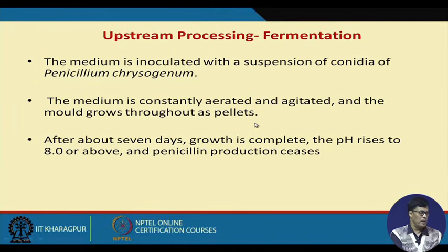Now, here again let me point out that in the case of fungal fermentation processes, we use the stirred tank reactor. In the stirred tank reactor, we use a mechanical agitator, and it has been observed that if we put the agitator on from hour 0, it will affect the growth of the organism to a great extent. So you have to keep the agitator off for some time in the initial phase of fermentation, and let the mycelia build up inside the reactor.